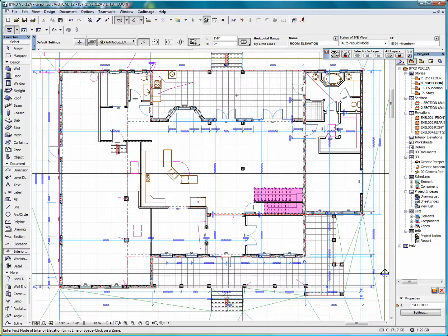Right now I want to pick up the elevations of this exterior lanai, and I want to include this little jog in the interior wall, this bay-like window. So I'll take the rectangular method and we'll place our cursor in the corner and click, and we'll drag a rectangle out to cover the extents of this particular room, and then we'll click again.